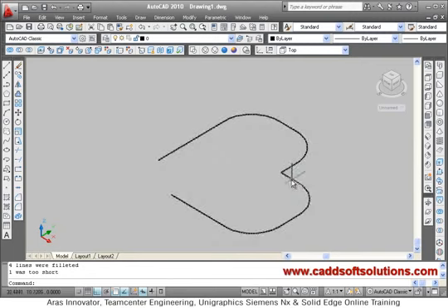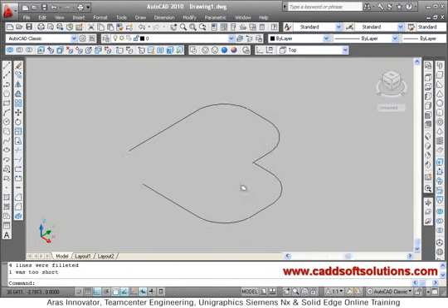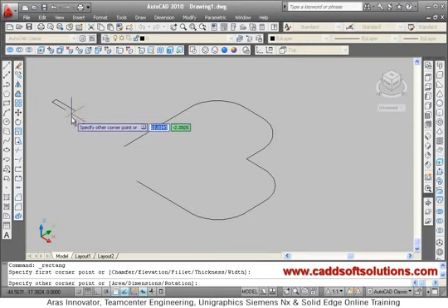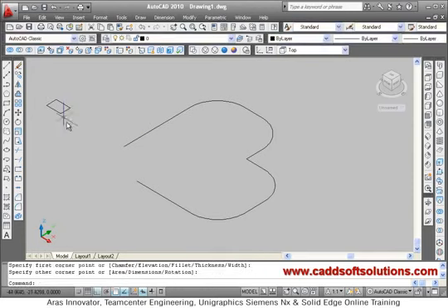So here the fillet radius cannot be given because a lesser distance was available, therefore it was not filleted. So you have to increase the gap. I want to create a rectangular duct like this, so I will create a rectangle of the desired dimension.